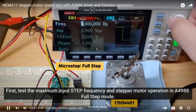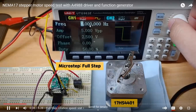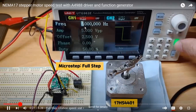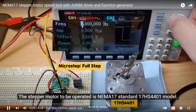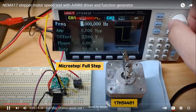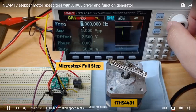As you can see over here, this is a stepper motor and 2 Hz frequency is given. This is the digital oscilloscope, and a function generator is there. See, this is frequency 1. 1 Hz frequency is applied to the stepper motor. Frequency will increase by 2. Frequency increases the speed of the stepper. As you can see, it is rotating in steps. It is rotating, again stopping, again rotating, again stopping. As you can see, frequency is 4. The speed of rotation is increased.